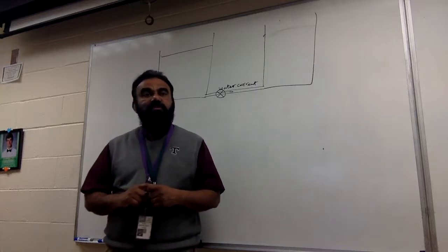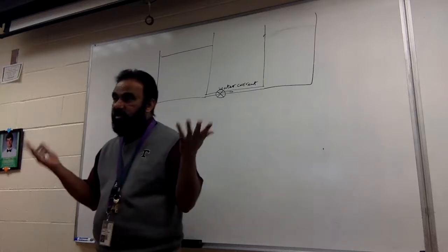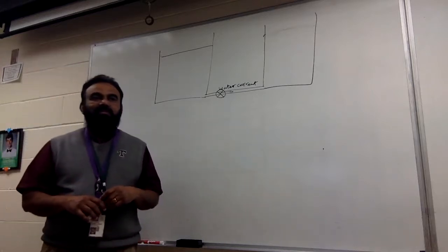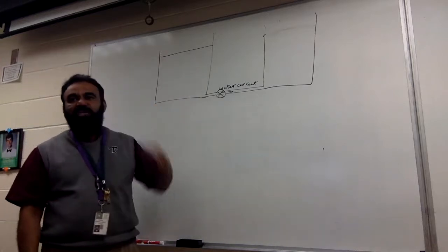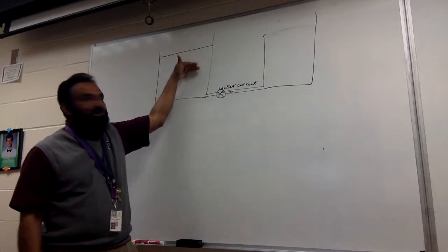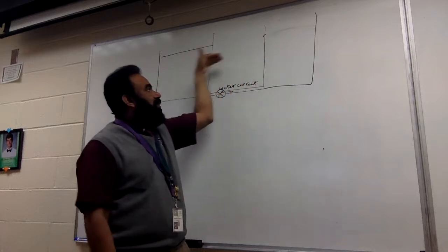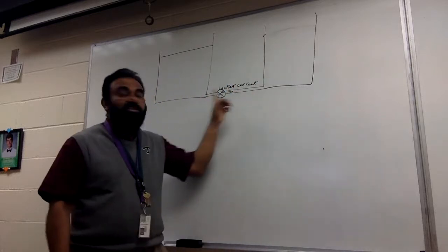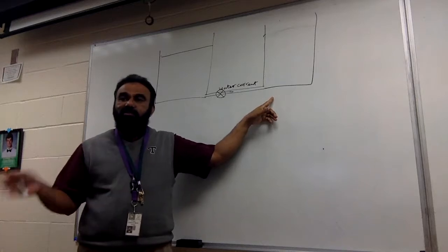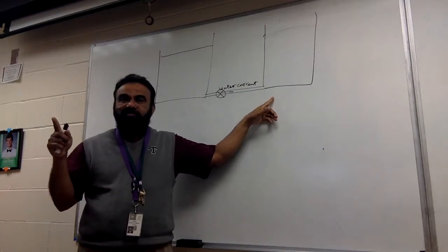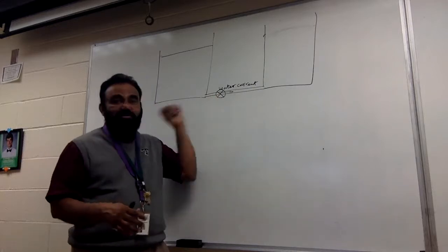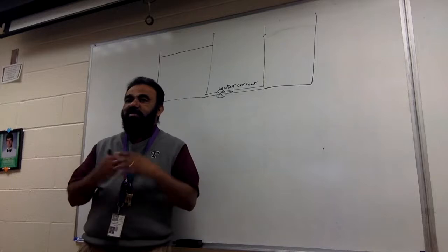Now my question: is the fan going to work continuously, forever? Why? Yeah, once the pressure is equalized, there's no flow. What happens here is this level is going to come down and this is going to go up. When these two levels match up, there is no pressure difference. And when there's no pressure difference, there's no current. Do you understand this concept? When there's no current, this turbine is not going to spin, therefore the fan will stop breezing me.